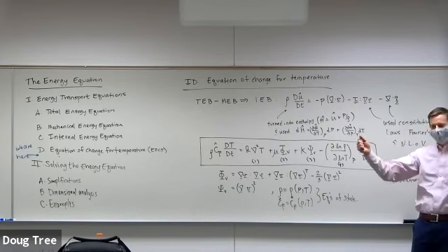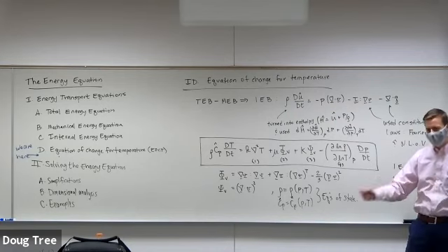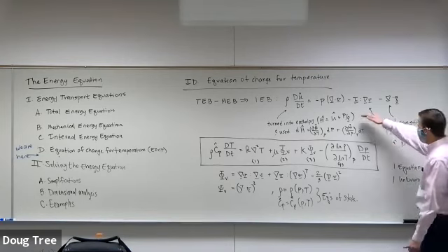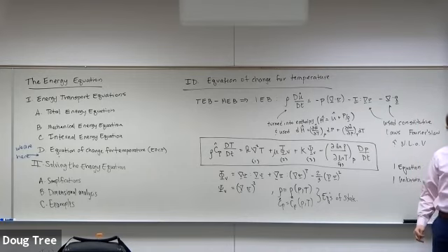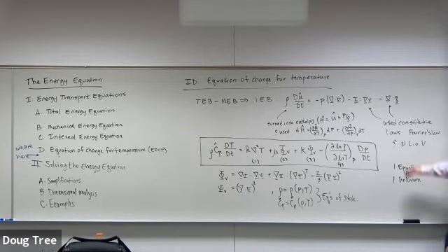And this was reversible volume expansion that gave us heat. So you could expand or contract and add heat or take heat away. This was an irreversible term that came from shear of fluids. So if I mix something, right, I've got all these velocity gradients, okay, that dissipate and lead to heat. And then this last one was heat transfer back and forth. So if I have temperature gradients, that moves the stuff around.